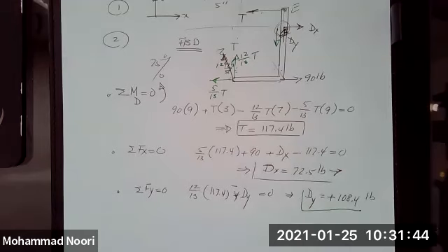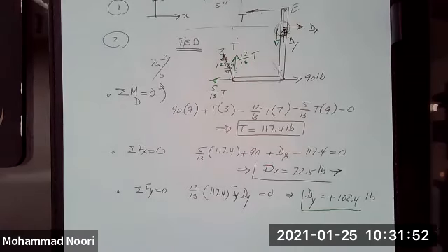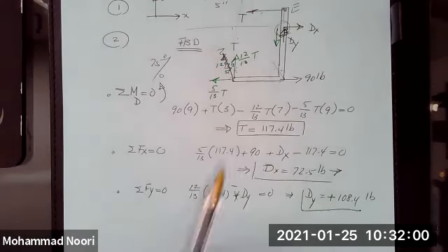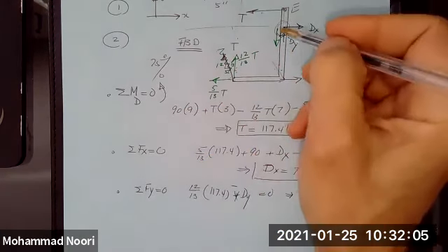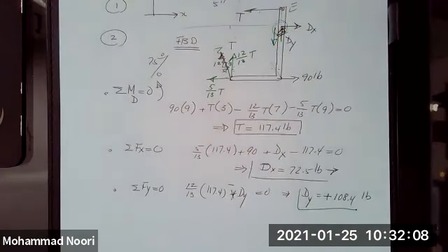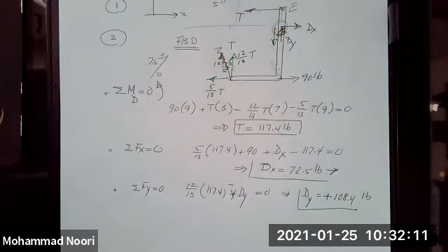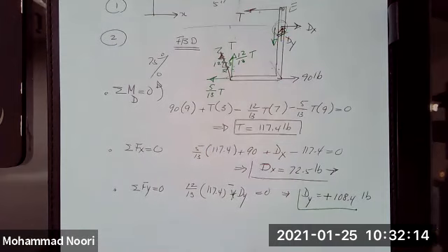No? Can we leave dy negative? I'm sorry? As the final answer, can we leave dy negative? No, no. Because the magnitude is always a positive value. And not only that, if you leave it as negative, that means your free body diagram is not right, because that force on the free body diagram actually has to act this way. So that's my strong suggestion. Any other questions? If not, let's do another problem.